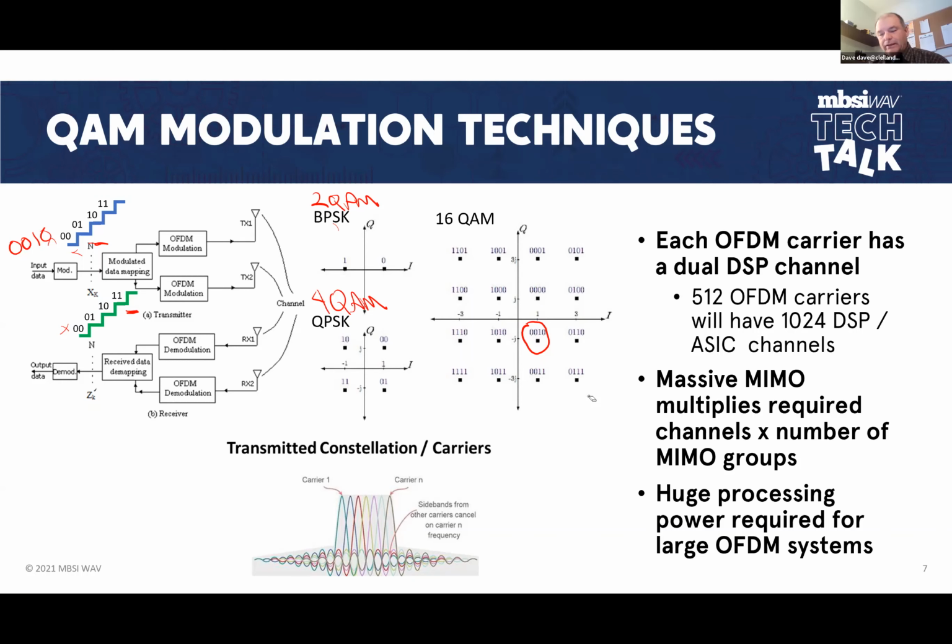Now, when I have an OFDM system like I'm showing down here, I've got these carriers that I'm going to transmit. I'm going to have one of these steps for every one of these carriers. So I am going to generate a slightly different frequency on every one of these carriers so that I fill up my transmit passband. I'm going to modulate them with data that my DSP stores when it receives it from the outside world, and I'm going to send it on to the other side.